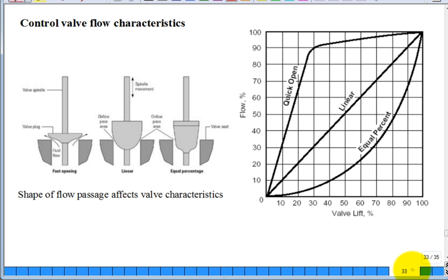So what do you do? Well, you have a control valve that has a different characteristic. They have 3 types of control valves being compared here. You have the equal percentage, the linear, and the quick opening. Okay, what are they showing here? This is the valve lift. If you think about it physically, you rotate the valve, typically you spin it and then it lifts off from 0 to 100%, from closed to fully open, or fully open back down to closed. So the valve lift, this is fully open. This is how many spins or seating it.